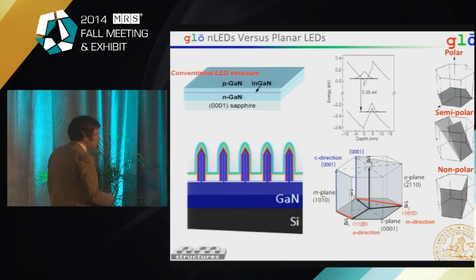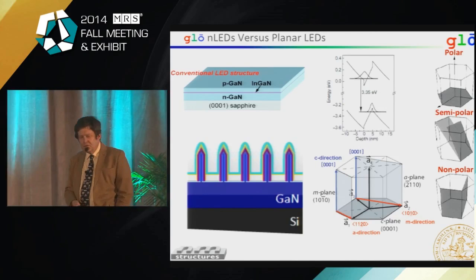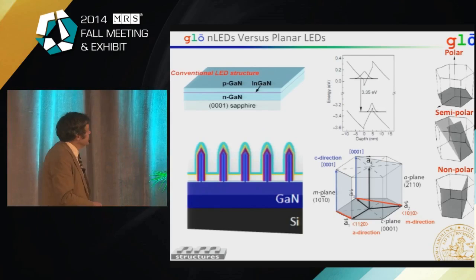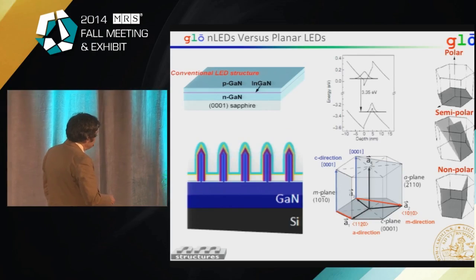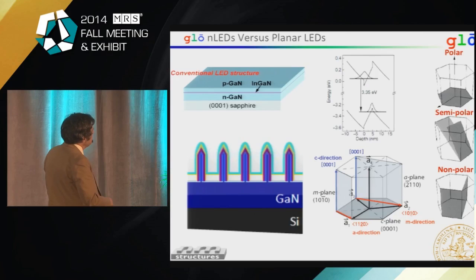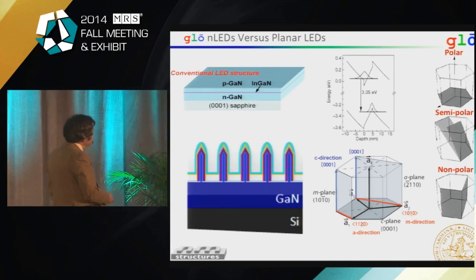They produce efficient UV LEDs and efficient blue LEDs. And they do that in spite of the fact that this material is really very low quality because of the lattice mismatch and the thermal mismatch between the sapphire and the gallium nitride. But somehow the physics of these LEDs permit these defects to be there without seriously affecting the performance. But there are still limitations.